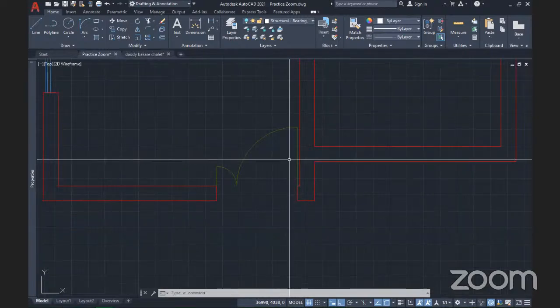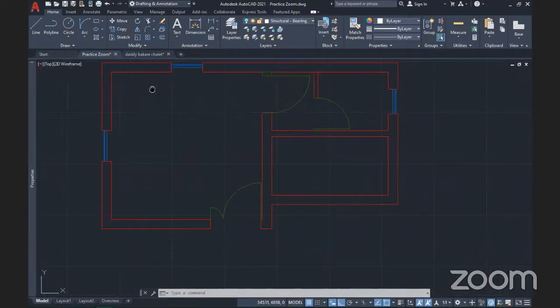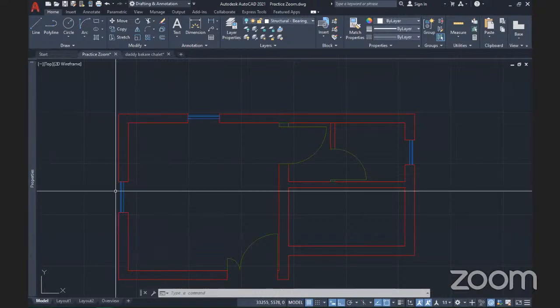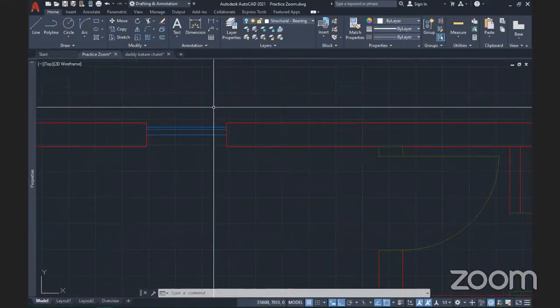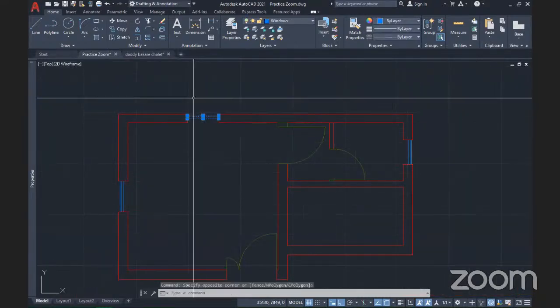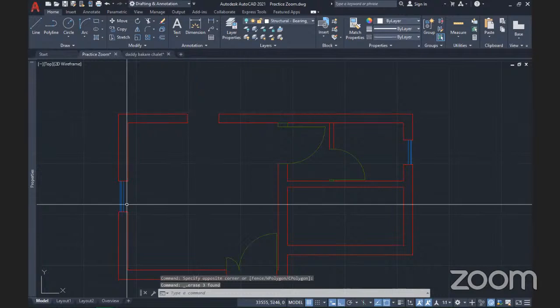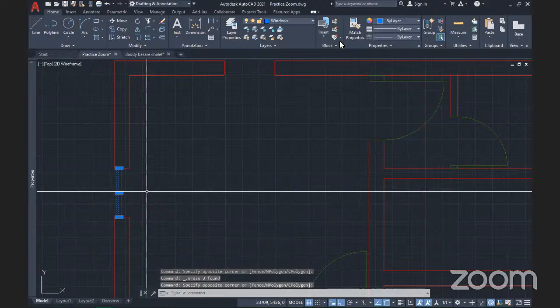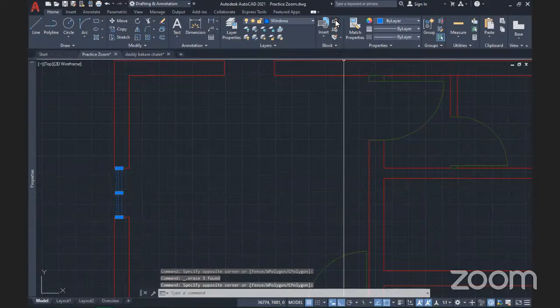And if you edit one, let's say for the windows, I have these two windows that are alike. So I can just create a block with one of them. I'll have to delete this one. For example purposes, I'll delete this one. And I can just create a block with this one. And let's say I go to create block. That's how to create a block.